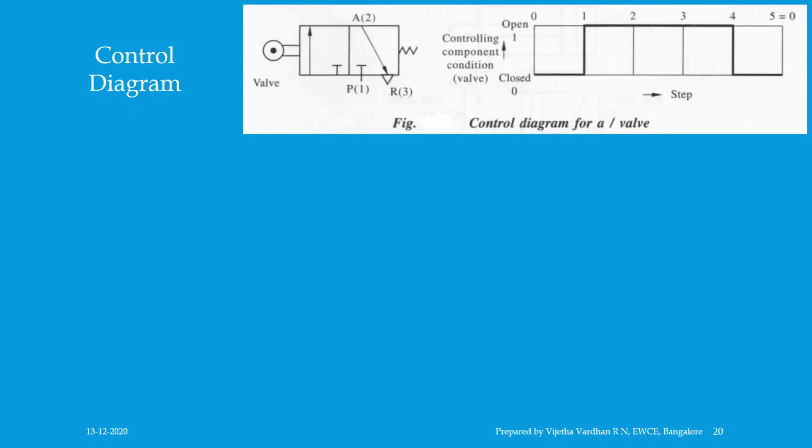Then let us understand more clearly what is called signal overlap. A memory device or a valve may receive signals from both ends from pilot valves. There may be a situation where signals are fed to both ends of the valve at a time, or a signal already exists on one end and the other signal is applied on the other end without removing the signal already applied at the other end. Such situations are known as signal overlapping.